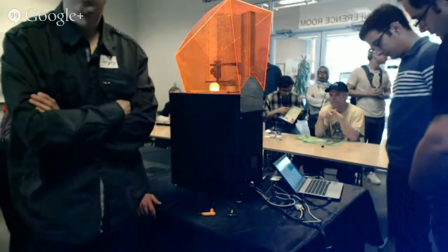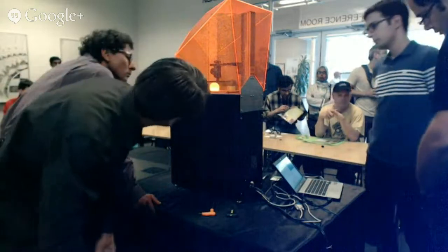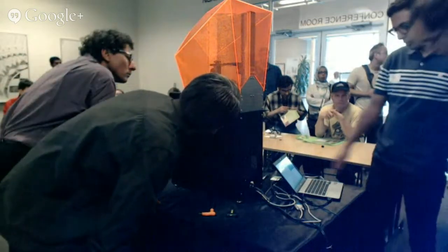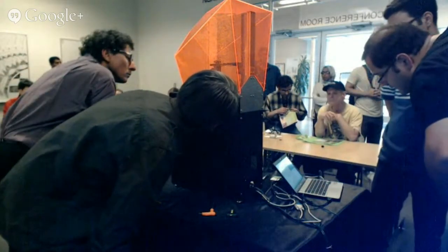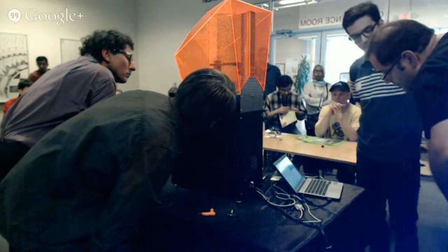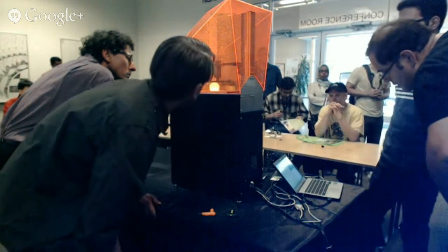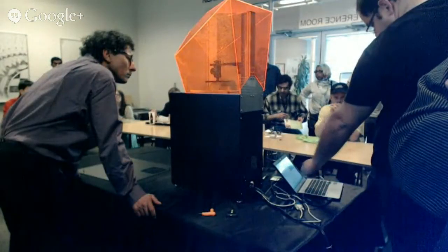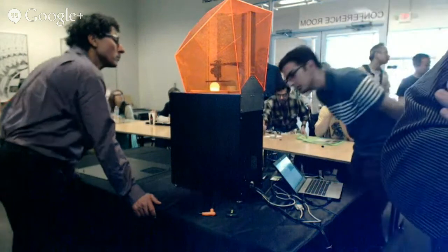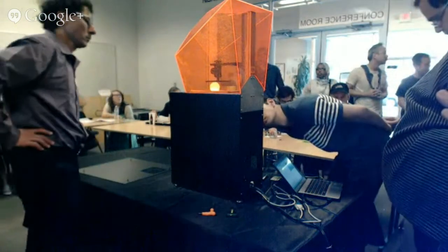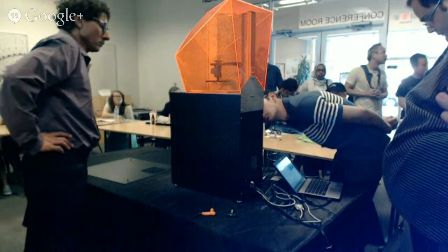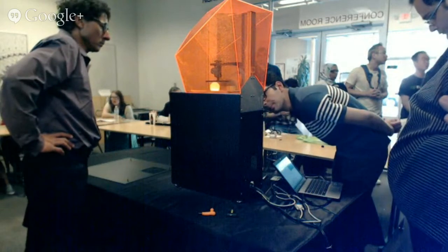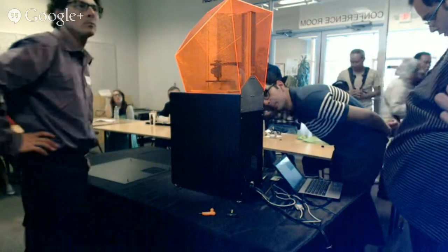So while the initiator reaction is going on, that reaction is going to catch the silicone. The silicone will also undergo chemical changes, right? And that means you want to be careful not to cure too much. You want to cure the minimum necessary to make your part conform, but not any more than that, because you want to save the life of your vat.